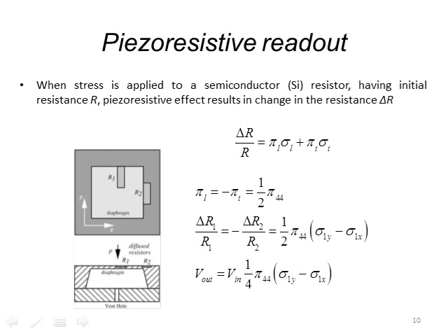So remember from the previous calculations that we had relationships for the stress in the membrane as a function of pressure. So in reality, the transfer function here, V out, is a function of these stresses, and these stresses are a function of the pressure. So this can be our transfer function. Now, what's interesting about these types of sensors is we can have 4 of them. We can make a full bridge. We will probably have a homework problem on this, and then you'll have to work through putting these into a particular bridge configuration and thinking about how this relates to a particular type of bridge.